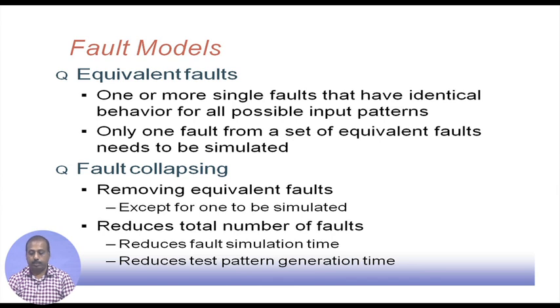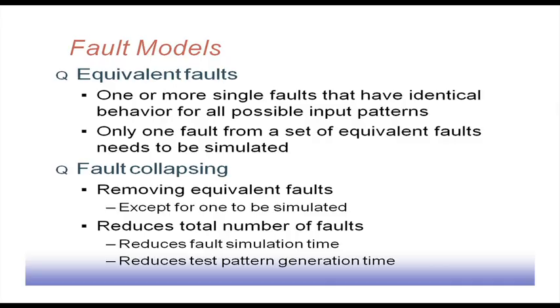Any test pattern set that can detect this fault will also detect the other faults in that equivalent set. So I do not need a separate test generation process for each fault in this equivalence class. This is the definition of equivalent faults.